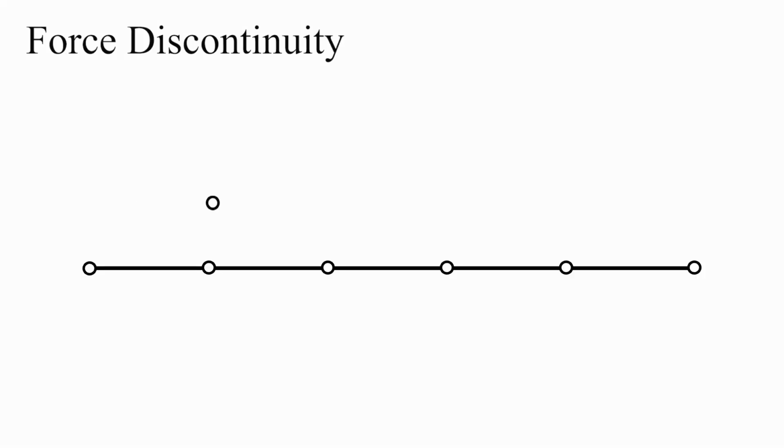To understand this problem, we consider the case of a single vertex moving at constant distance to a sequence of collinear elements, sufficiently close for collision response to become active. A straightforward way of modeling contact is to select the closest primitive, the first segment in this case, and to construct a penalty function based on the distance between vertex and segment. The contact force direction is then collinear with the segment's normal and remains constant as the vertex moves across the